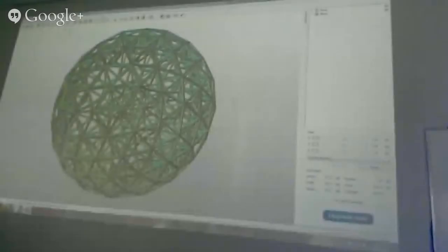And the cross here is for repairing. Sometimes you will see there are errors in your mesh. For this one, it's very clean. It has no holes, no invalid orientation. All these things are zero, and you got only one shell. This is a perfect model. It will help you fix it if you do the automatic repair. But since this is a free version, it won't repair everything. If you have something more complicated, you will need to go to their cloud version.